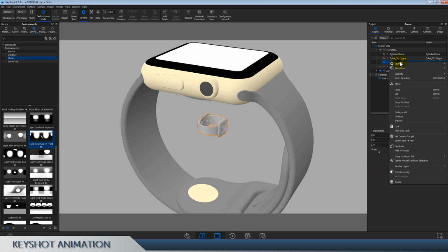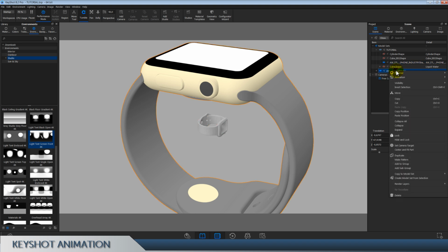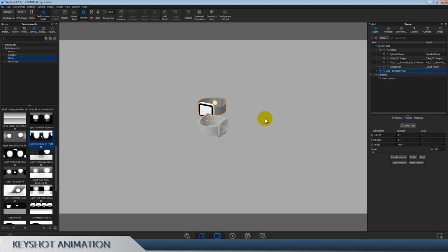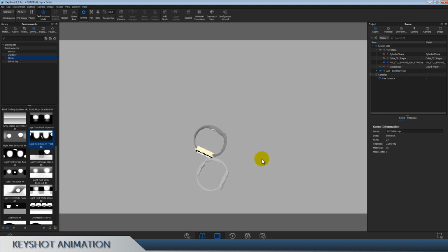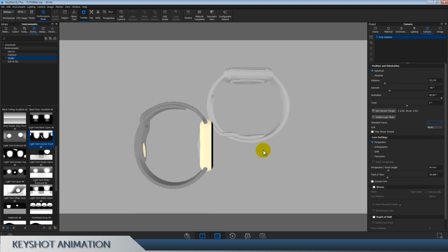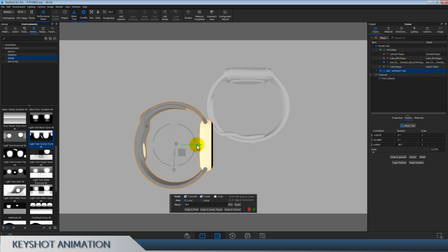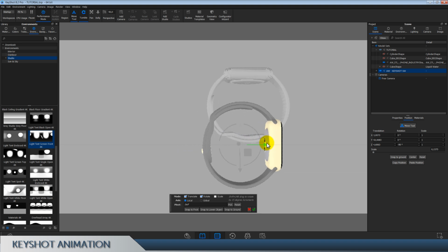If you right click on this STL watch from Blender that we imported and you say copy position, and you go here and right click, paste position, you will notice that we have a perfectly scaled model. It's not perfectly set to position, but it's easy to do. So let's switch to top view and do that, and I hope that this tip is gonna help you in some other projects as well, not only for this one.